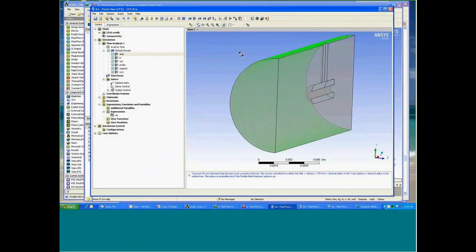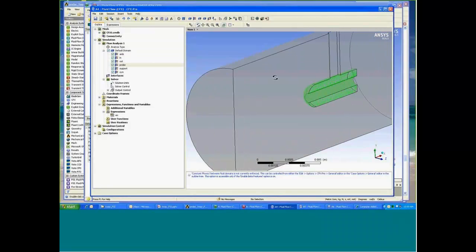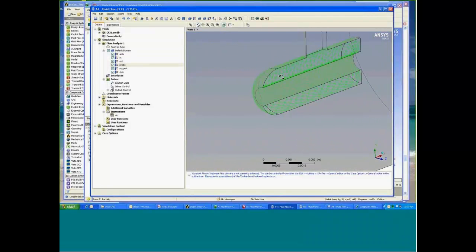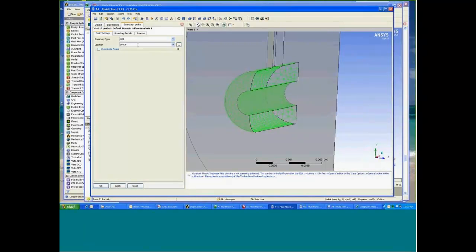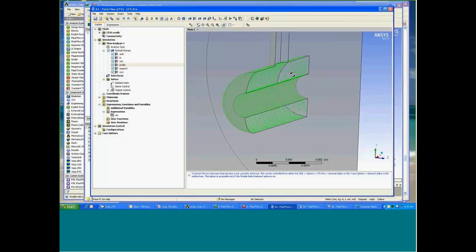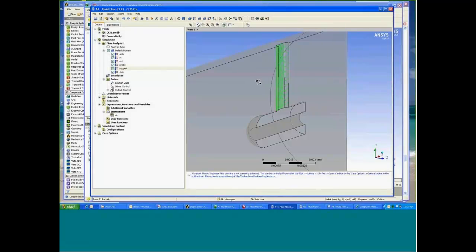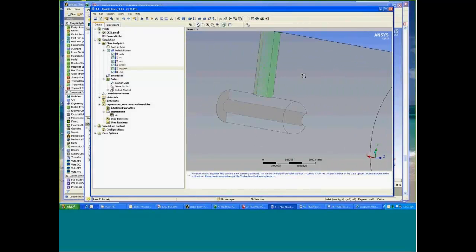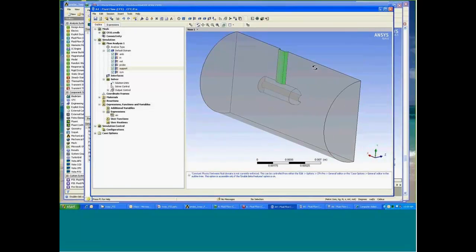And then I have two solid surface boundary conditions, right? One is the probe itself, okay? That is the cylindrical-like surface of the probe and the internal flow passage wall, right? Two parts constitute the surface. It's a wall. And I have the support, which is the stem that holds the probe to a fixed point. And I have these as boundary conditions as well. So by setting up this case, I have the name selections assigned, and the inflow and outflow boundary conditions assigned. I'm ready to run the analysis.